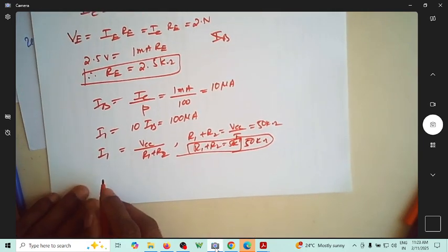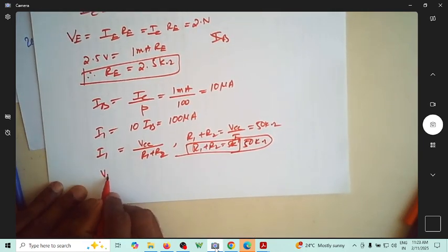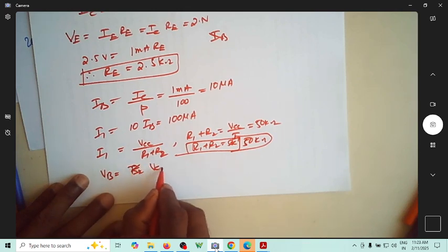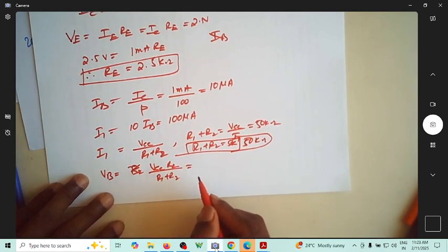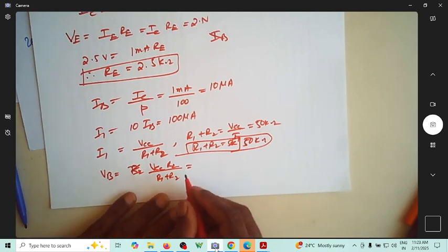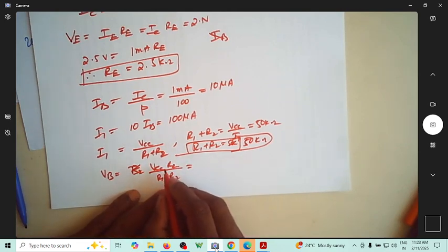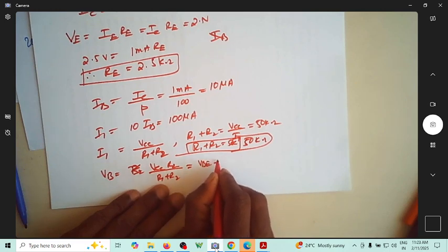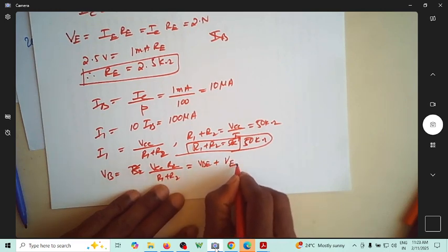Then what else do you have? You have another expression. VB is VCC times R2 by R1 plus R2. That should be equal to VBE plus VE.